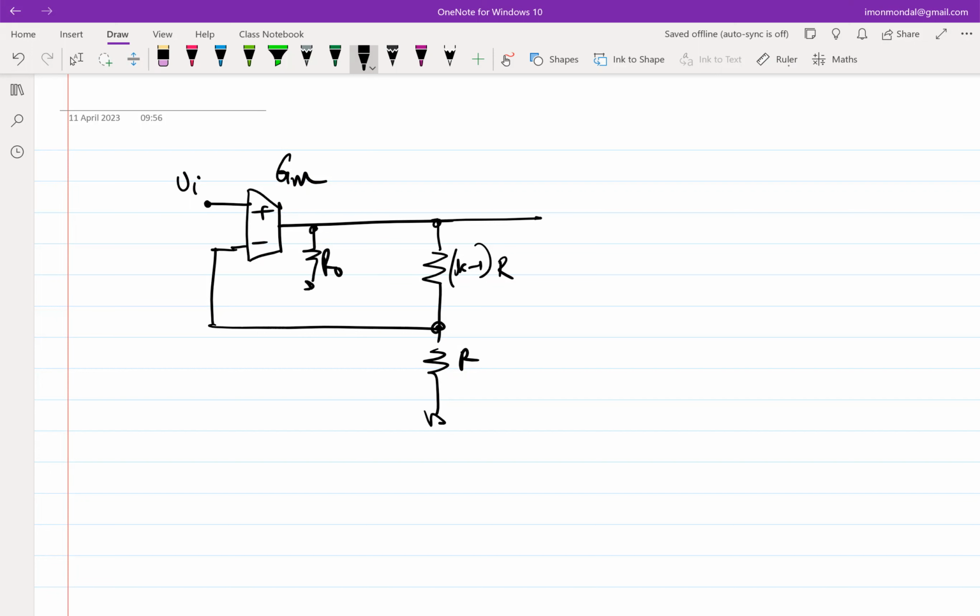So now tell me one thing quickly before we go about discussing this in more detail. What happens if I add a resistance RL here? What aspect of this negative feedback loop will change with the application of RL? The gain of the loop will reduce, right?